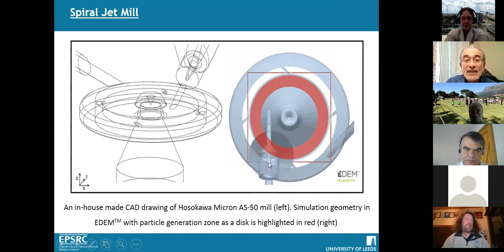And this injector nozzle basically induces the flow of particles into the mill. As you see here, this is the high pressure feed nozzle, and this is the cone where the particles are introduced, and there is an induction of air in here that accelerates the particles and introduces them into the system. So the pressure here is larger than the operating pressure that we have there.